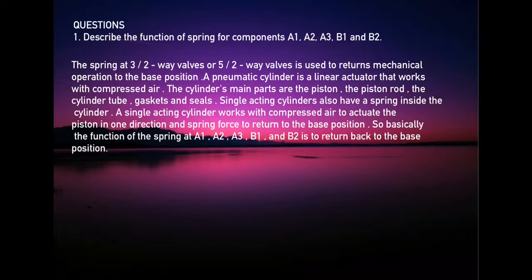For question number 1, lab activity 1. Describe the function of spring for components A1, A2, A3, B1 and B2. The spring at 3/2-way valves or 5/2-way valves is used to return the mechanical operation to the base position. A pneumatic cylinder is a linear actuator that works with compressed air.